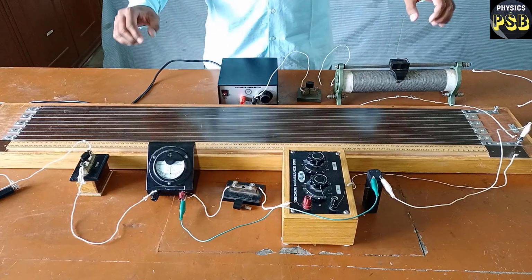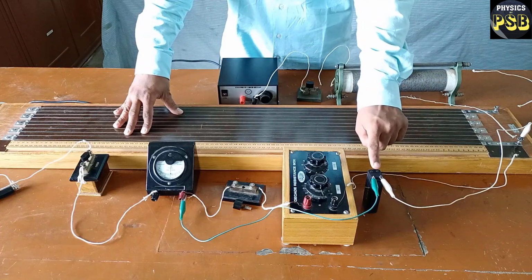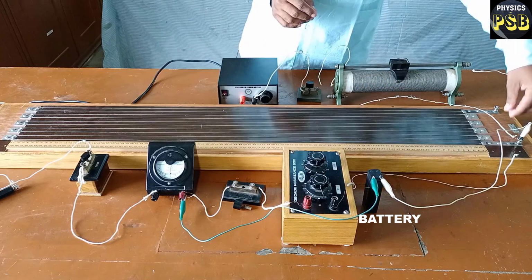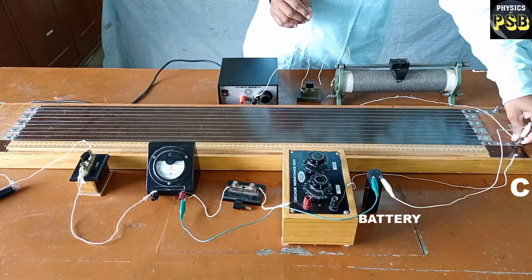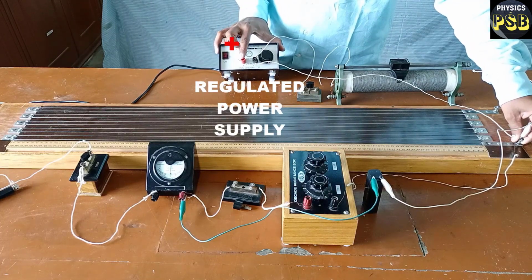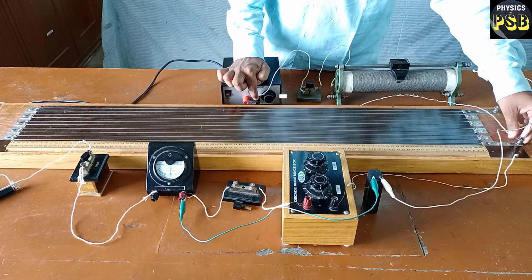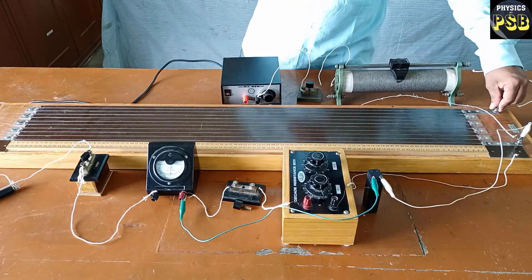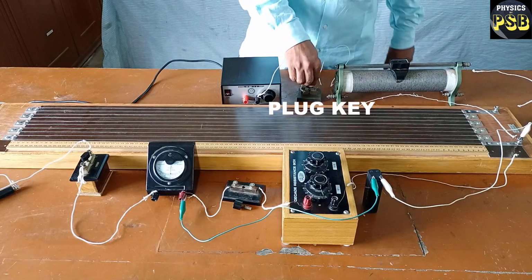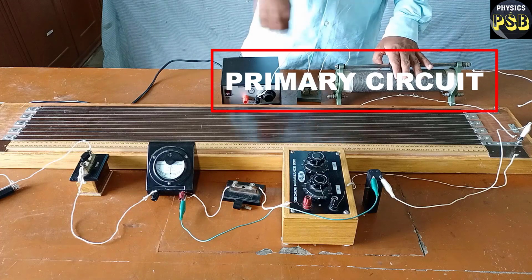I have connected the potentiometer to measure the internal resistance of a cell or battery. For that, this end of the potentiometer is connected to the positive terminal of the battery or power supply. Then the negative terminal of the battery or power supply is connected to this end of the potentiometer wire through a key and rheostat. This forms a primary circuit.